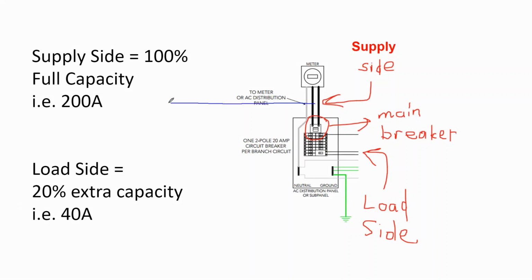Lastly, with interconnection, there's one thing that I want to mention, which is standard solar design. You're either intercepting the conductors between the meter and the main breaker, or you're landing the solar array down at the bottom of the bus bar. There's one other piece of material that is currently not part of solar design that I think will become increasingly popular in designs in the future, which is to also reserve the top of the bus bar for an emergency power supply.